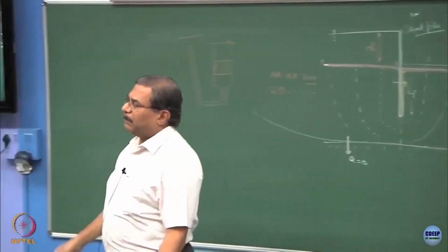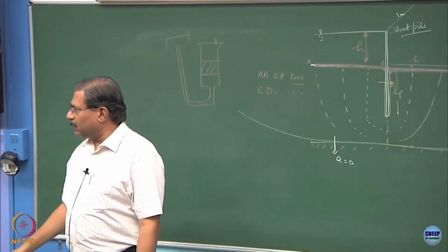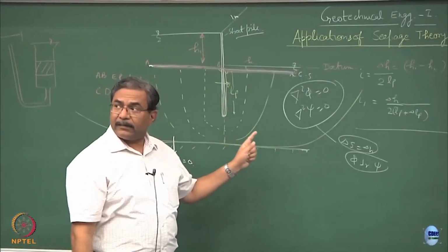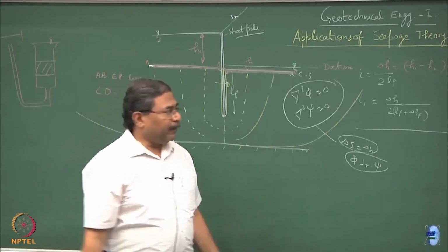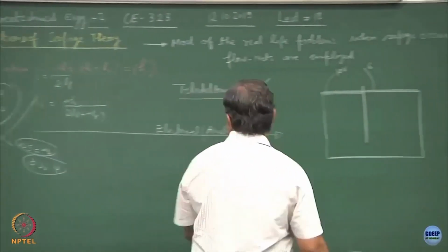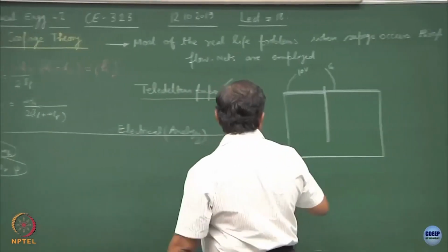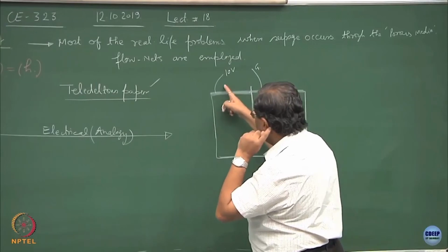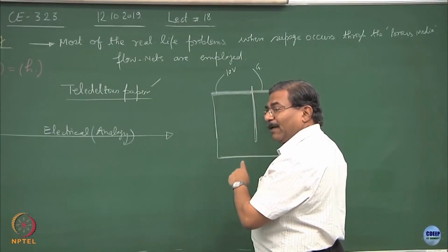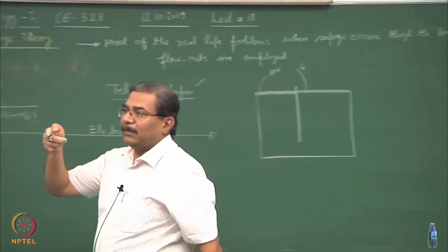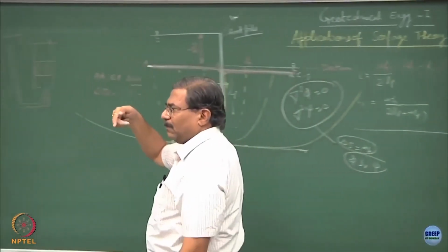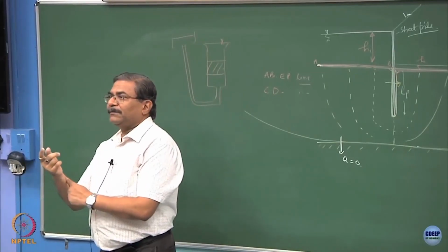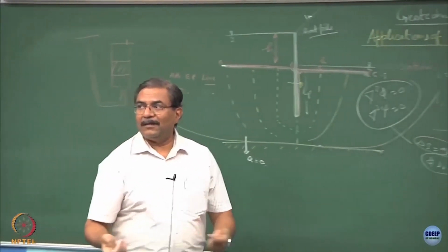So, either you do mathematically, you can solve these differential equations, is this okay, and you can plot the phi and psi domain, you get the flow net, clear. Easy way would be what engineers will be doing, this is what mathematicians will do. Engineers will use this paper, scale down the whole project, apply certain voltage here, 0 voltage here, and then take a probe. You know these conducting probes are there, what do you call them? In multimeters you have probes, is this okay?